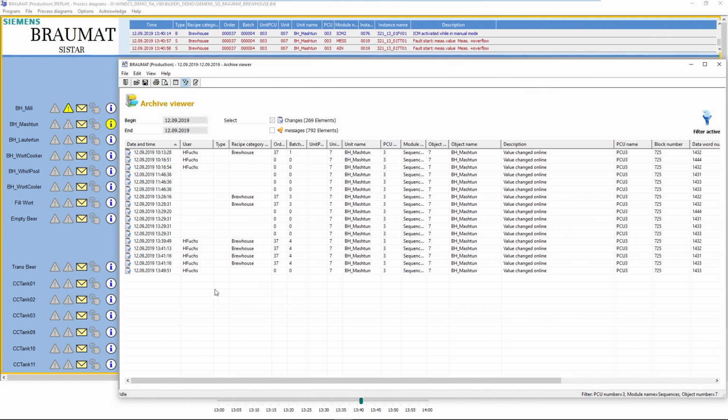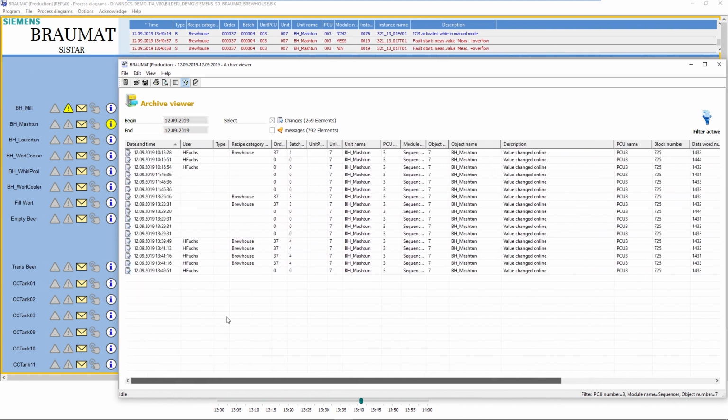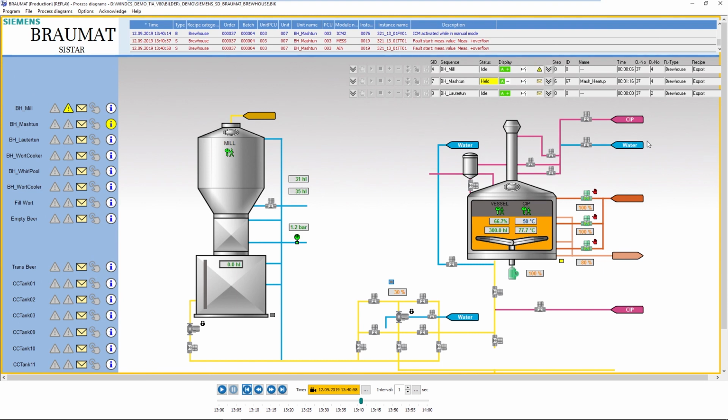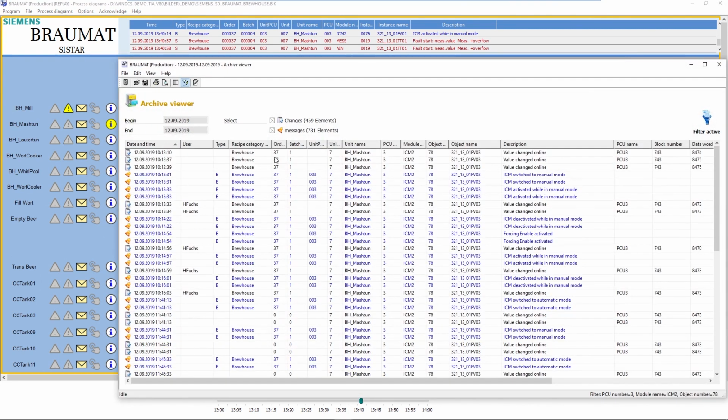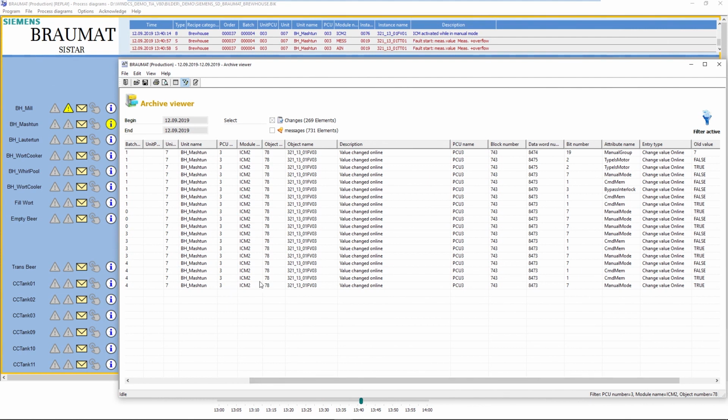Each operation is entered here in a log file with a record of the corresponding user, the aggregate, i.e. the mash pan, and the attribute that has been manipulated. In fact, one operator, Horst Fuchs in this case, did the manipulations. You can practically ask him if he can still remember. What is also noticeable is that the steam valves here are set to manual. I will also get this presented in this changelog, with the entry user, valve tag name, and which attribute did get manipulated.